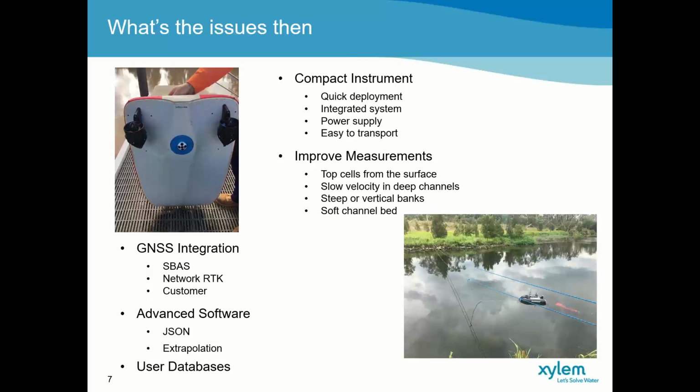Extrapolation. Current ADCP solutions, irrespective of the brand, don't provide appropriate extrapolation tools in their software to perform velocity extrapolations on the profile. And that was one of the aspects that was directing a lot of users to use third-party solutions such as the USGS Xtrap and QREF.